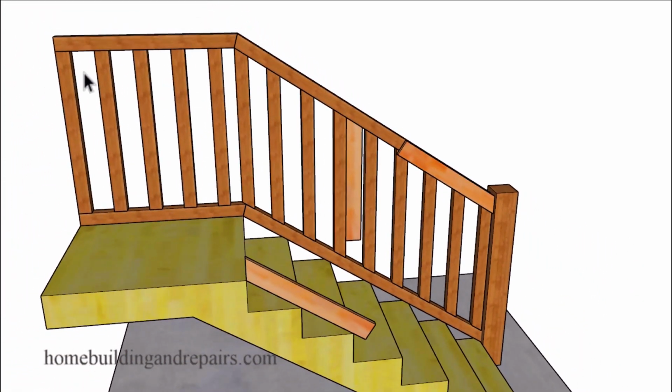So basically what we're looking at here is a 90-degree angle here, 90-degree angle for our balusters here, again 90 degrees top and bottom cuts. And then we have the angles here so that these boards will miter together. And then the baluster boards at the top and the bottom will be the same, along with the upper and lower rails if they're going to connect into a newel post.